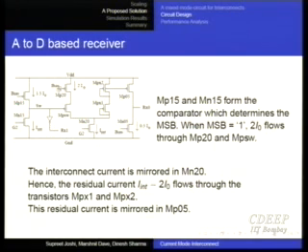So it is just make a pipeline converter for 2 bits. So essentially the first one, and then depending on that first one, either you subtract I0 or don't subtract I0. Okay? So you can make any architecture. This is one architecture. For 2 bits, what's the big deal? You can make a 2-bit pipeline converter like nobody's business. Okay, and it will be quite fast. So that is what you can end up doing.